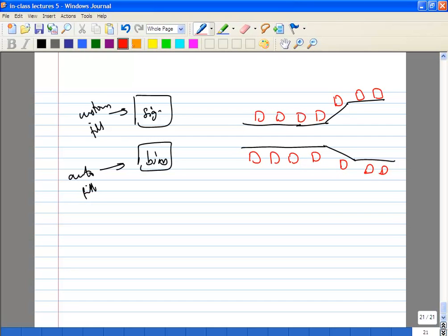And typically what you'll have to do is, around inductors, you can leave out fill. Normally around the inductors, the foundry will give you some waiver, because obviously the inductor is going to be huge. It may be 200 microns by 200 microns, and that means that area is definitely going to have low density for lower metals. Okay, and you can't do anything about that. Usually the foundry will review the layout and give you a waiver.